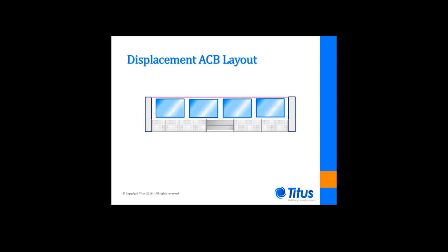This slide illustrates a classroom fitted with TAO terminals. Primary air and the chilled and hot water supply is delivered through the ceiling cavity of the classroom. These services then drop through either chases provided by others or duct covers furnished by Titus and mounted in the two corners of the classroom adjacent to its outside exposure. The water supply for all of the TAO units can be provided through one chase and returned through the other.